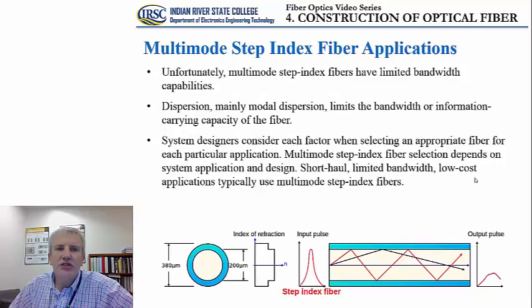What would be the applications of the multi-mode stepped index fibers? Obviously, due to the fact that the dispersion in this type of fiber is more pronounced, these fibers will have limited bandwidth capabilities, and therefore limited applications. Usually shorter distances would be the applications of this type of fiber.